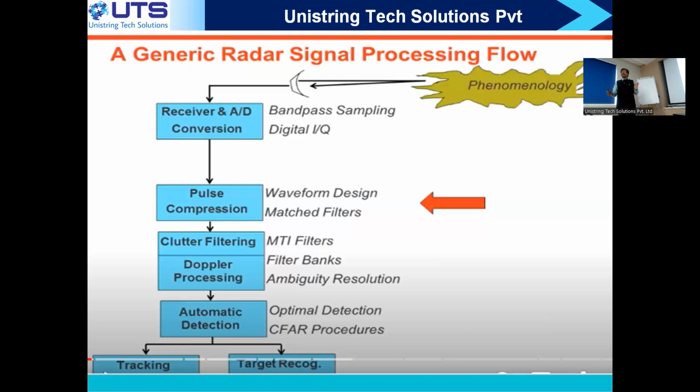Again, it's a trade-off. You want to tune your signal processing for reducing your false alarms, but then you will sometimes miss small targets. I want, let us say, to detect all small targets also, slow moving targets also; you give a lot of false alarms. You understand? Because you are going close to the zero Doppler frequency in the range Doppler map, where the clutter leaked energy sometimes may get detected as a Doppler component.